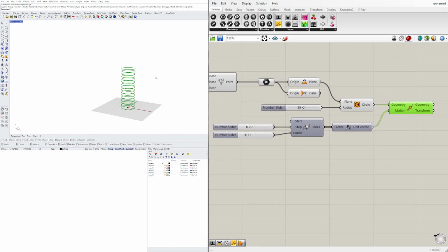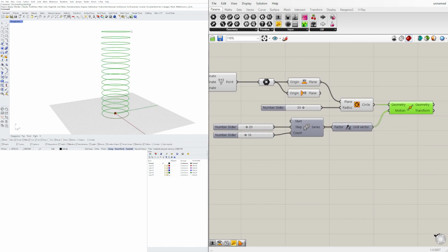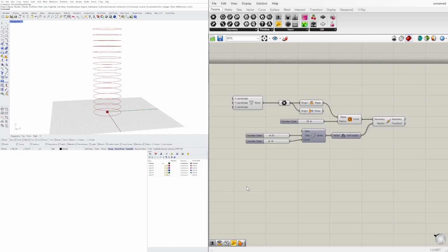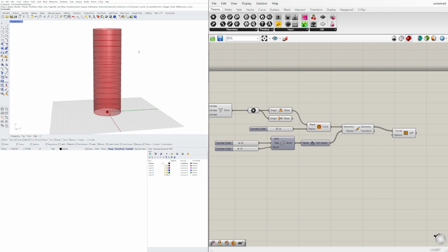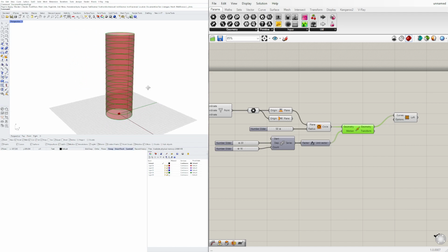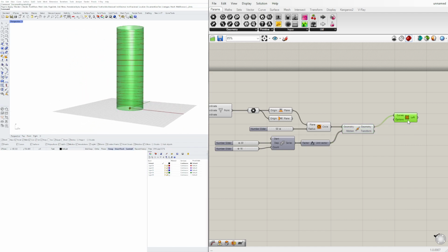So now that we have these copied, now the idea is going to be to create a point that we can use as our point attractor. So automatically with this, if we brought in a loft component, we would have a pretty straightforward extrusion up, just going through all of these curves. But now let's go ahead and take this and let's change the scale of all of these circles using a reference point. So I'll go ahead and unplug this using Control. Now let's take this and create an endpoint going through all of those.